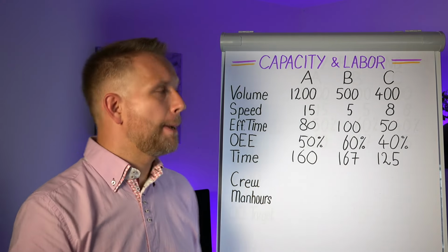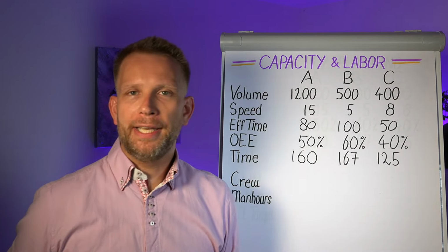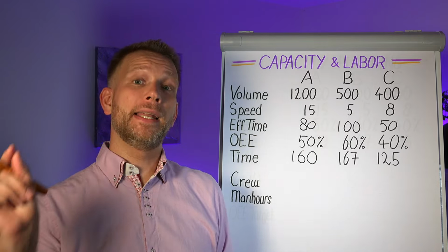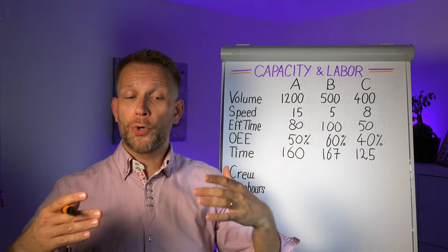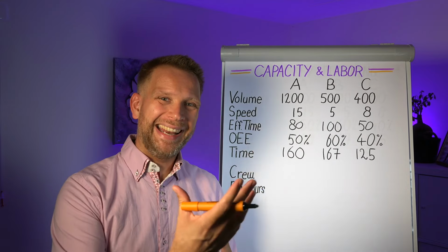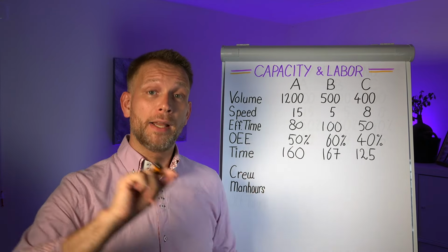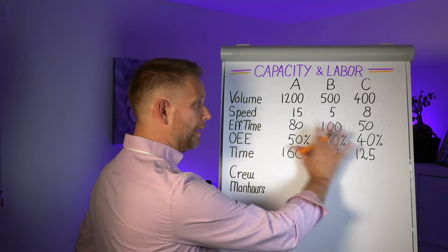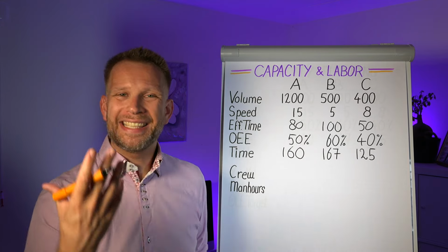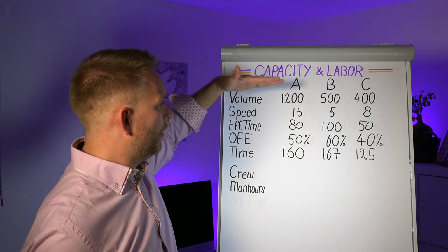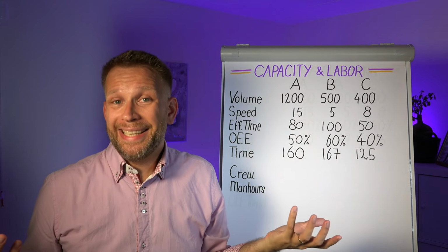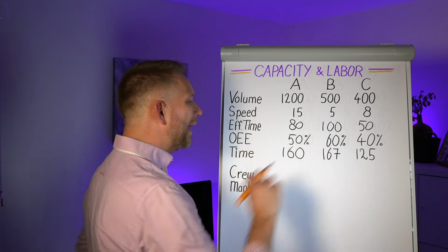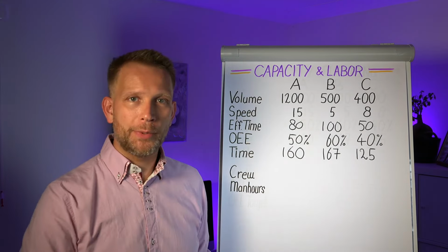on that machine. And I sort of said this would be per week, but we'll get to that in the next video on this topic, because this is also the basis for your capacity planning and your asset utilization planning. But right now, we just take this as granted. This is what we are planning to do, how fast we know the machine is, our OEE as we know it, and then how many machine hours do we need.